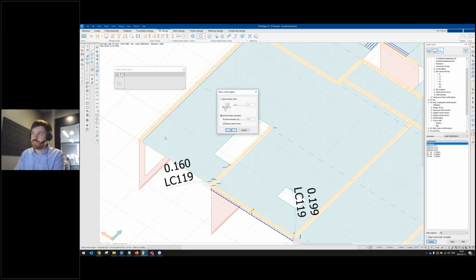So in this region, you probably will have some reduction due to the size of the wall and that the force is going straight down to the wall instead of shear, because it's modeled as shell, and shells don't have any analytical thickness, and that's the reason why you often want to apply some kind of reduction in these zones.